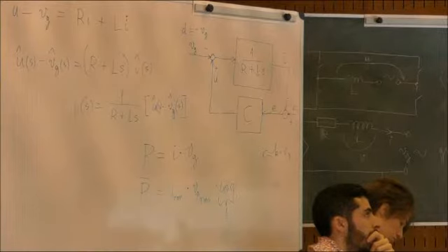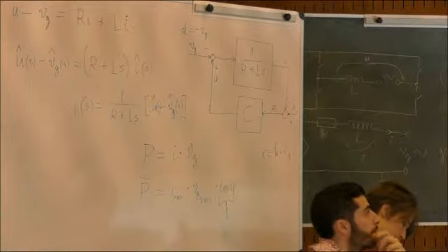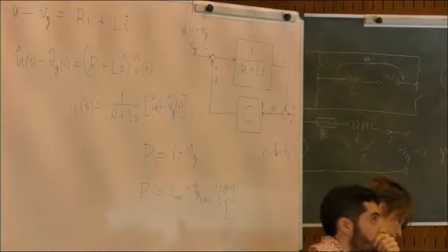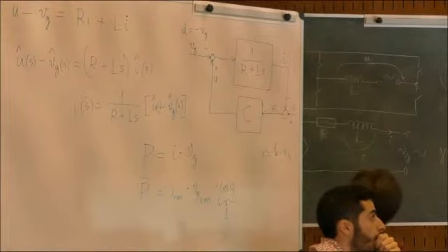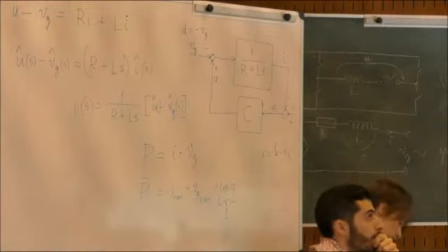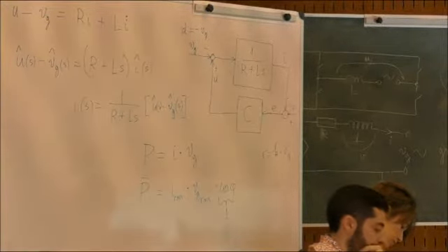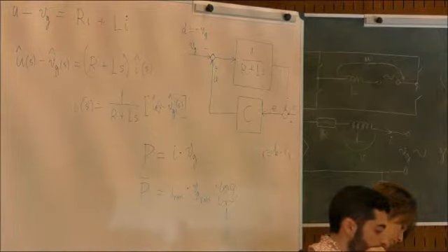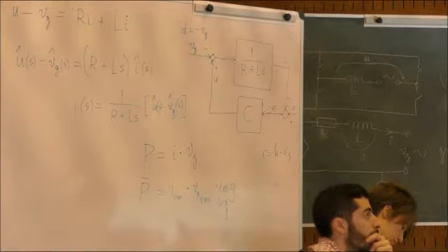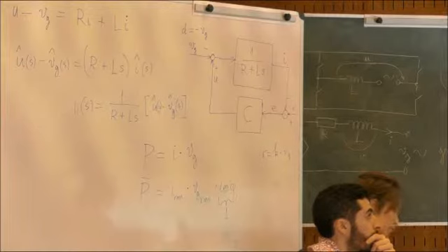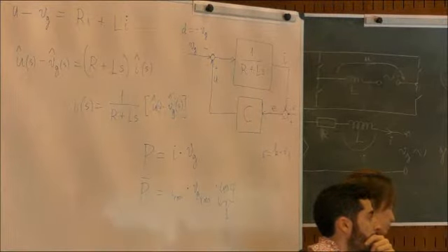So ideally it should be 0, because there should not be any components other than the fundamental component. But there are, and so this ratio is expressed in percentage, and it should be something like 2-3%. It depends, each country has its own regulations on how much is allowed. So in general, you try to take a current which is close to sinusoidal. Okay, but nevertheless the grid is distorted. It is not exactly sinusoidal.